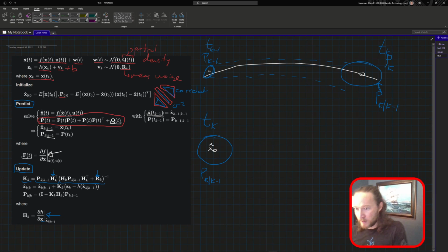So now with our Kalman gain, we can actually update to our new state, X of K, as seen by the kth update. So we take our previous state and we add the Kalman gain times what we call the measurement residual, which is the difference between where you are and where you're not. Maybe you've heard that kind of silly word game where somebody tries to describe navigation by determining where you are but where you're not. That's what this is. This is the residual.